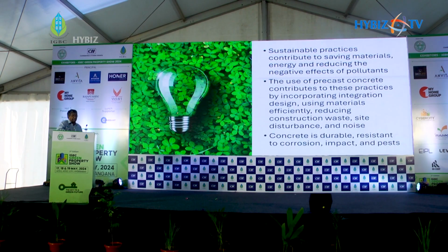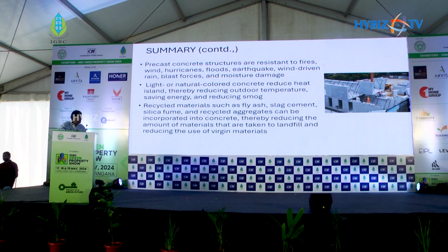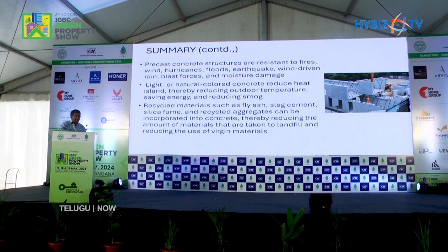Coming to the summary: sustainable practices contribute to saving materials and energy and reducing the negative effects of pollutants. Use of precast contributes to these practices by incorporating integrated design, using materials efficiently, and reducing construction waste, site disturbance and noise. Concrete is durable, resistant to corrosion, impact and pests. Precast concrete structures are resistant to fires, wind and hurricanes. Light or natural colored concrete reduces the heat island effect, thereby reducing outdoor temperature, saving energy and reducing smog.